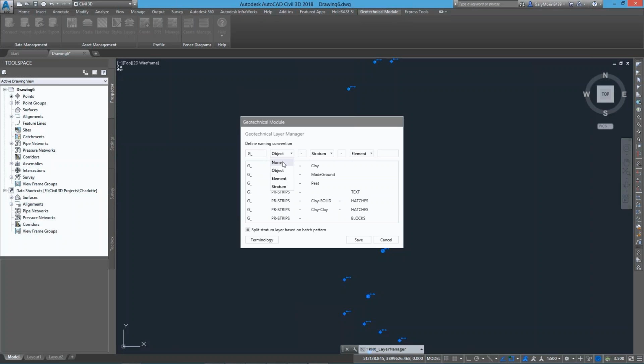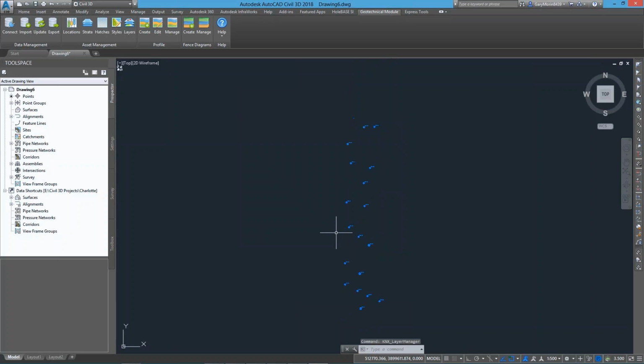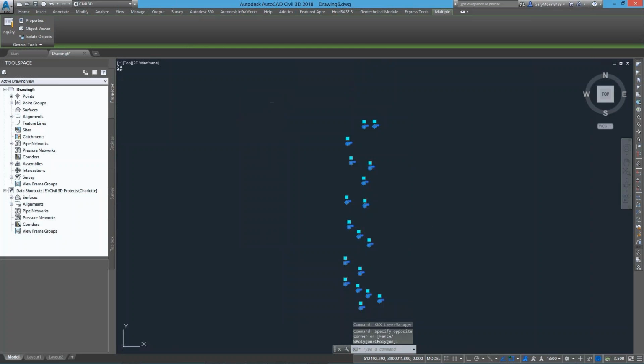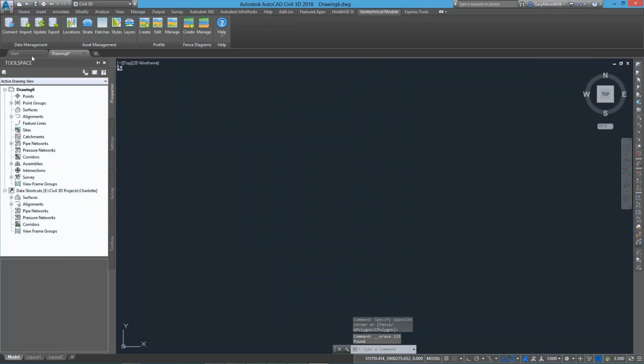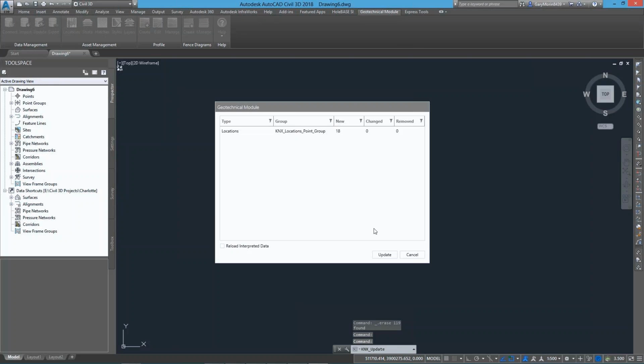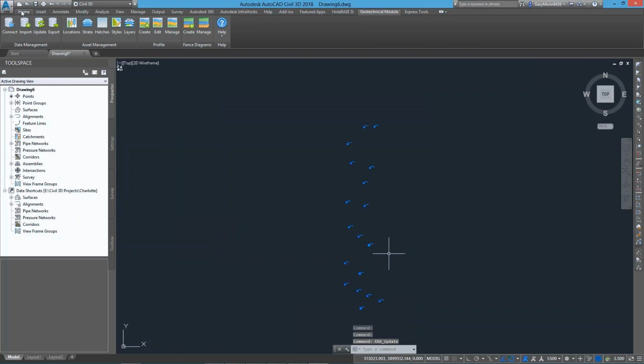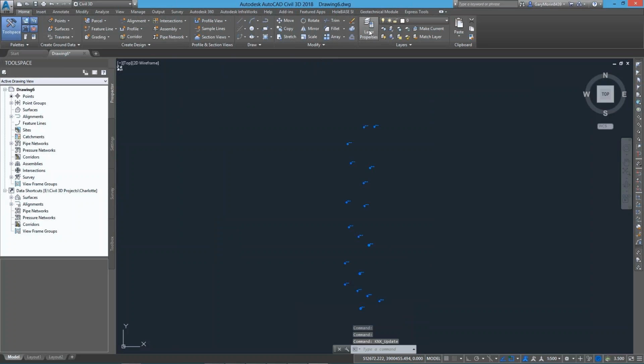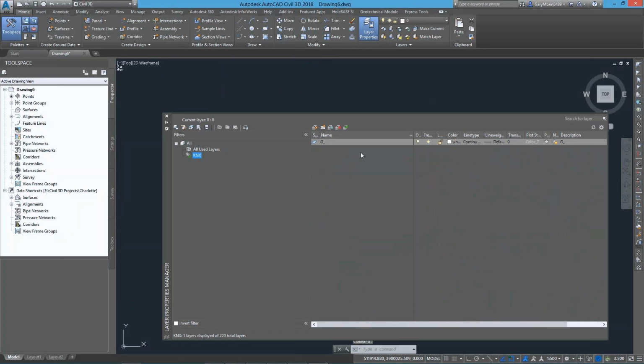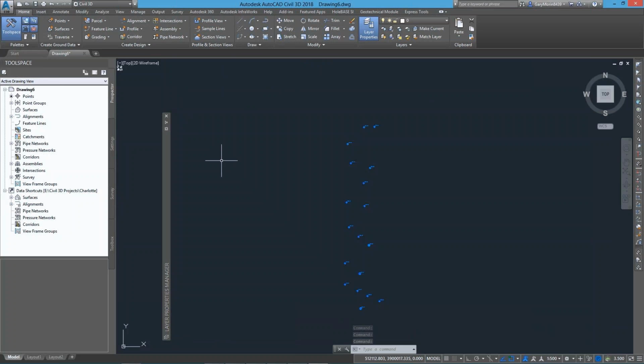Let's have a prefix for all my geotechnical layers. And in fact, I'm going to tell it don't bother doing anything else. So we're going to put all of our geotechnical data on a really sophisticated layering system called G_. That's what my CAD manager insists, that all geotechnical data has to go onto a layer called G_. Wonderful. There we have it stored that way.